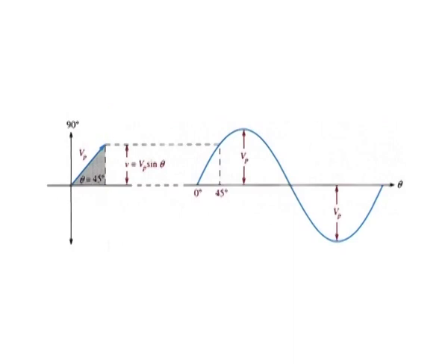Thus, the opposite side of the triangle, which is the instantaneous value, can be expressed as V equals V peak sin theta. Recall that this formula is the one stated earlier for calculating instantaneous sinusoidal voltage. A similar formula applies to a sinusoidal current, where I equals I peak times sin theta.